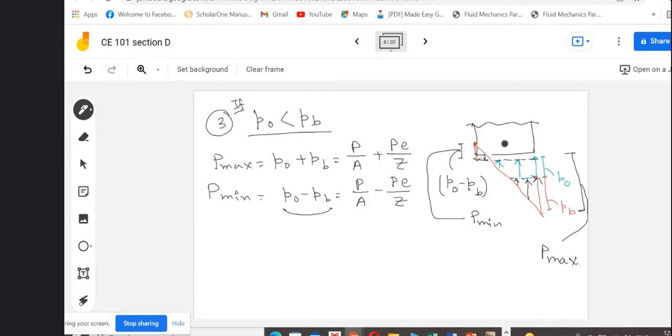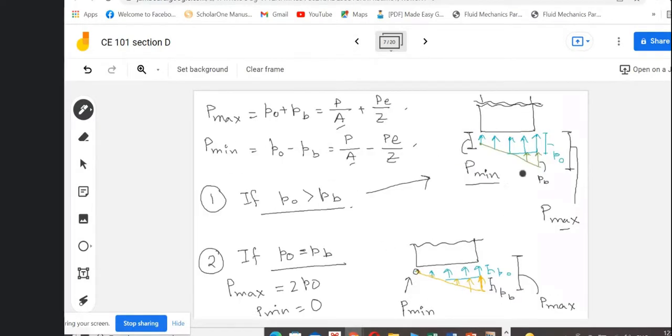So the stresses below this column, one part is in the compressive zone and a small part of it is in the tensile zone. Whereas for the other two conditions, for say condition 1, both the stresses were in the compressive zone as none of them were in the opposite direction.